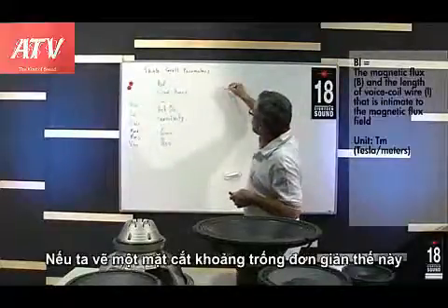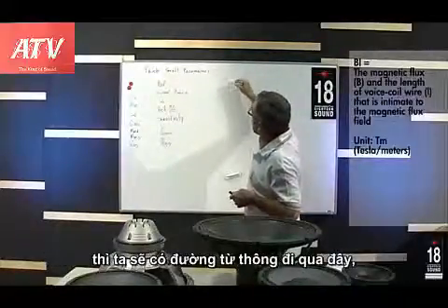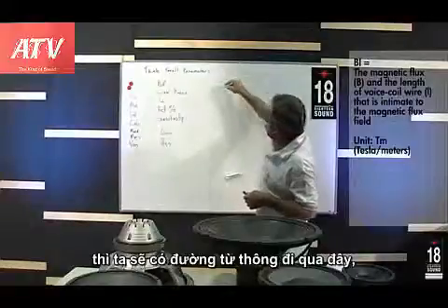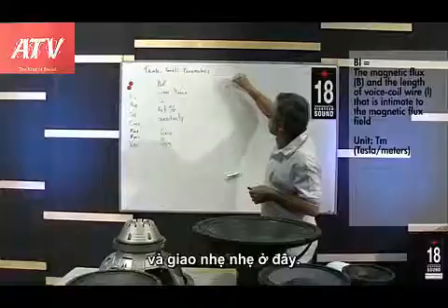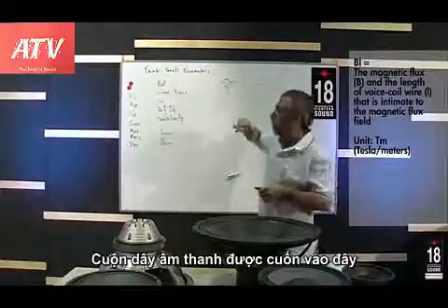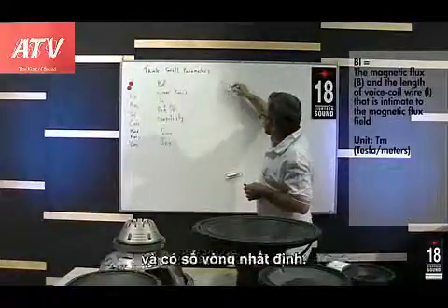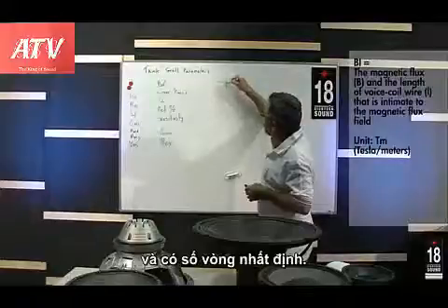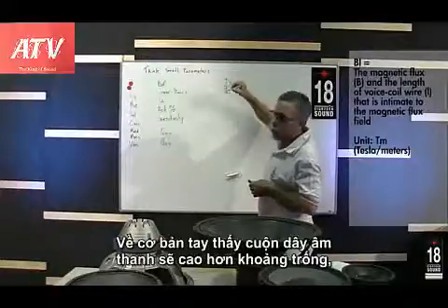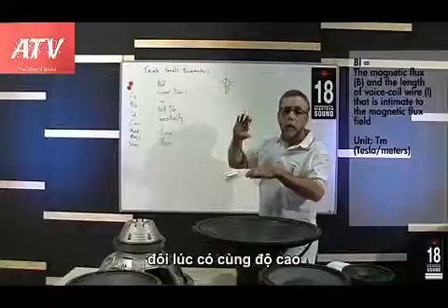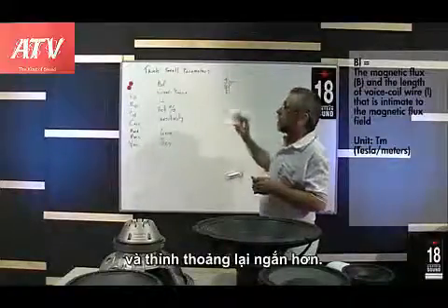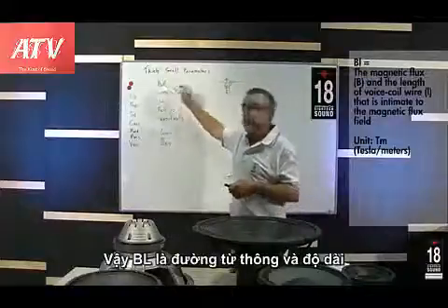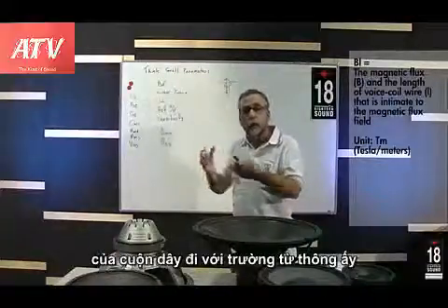So if I draw a simple cross-section of the gap, we have magnetic flux that travels across, and there's a little bit of fringe. The voice coil is wound on its former and has a number of turns. Typically we see voice coils that are taller than the gap, occasionally equal height, and sometimes even shorter. So the BL is flux and length of wire that is intimate to the flux field.